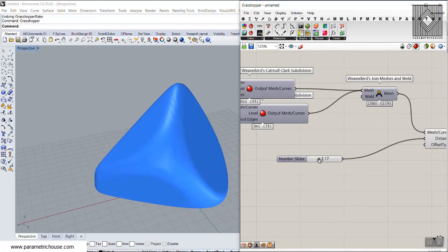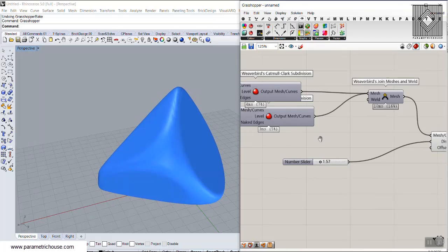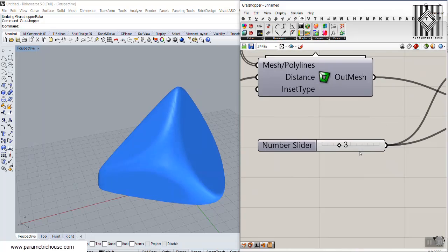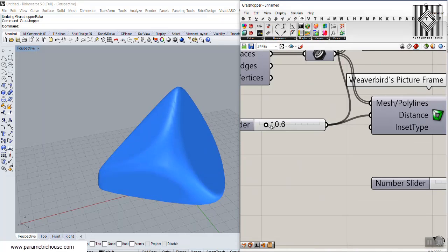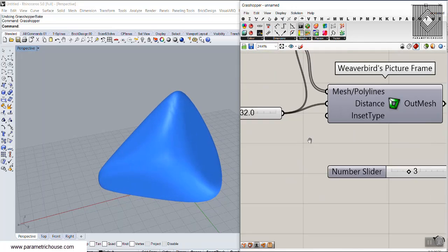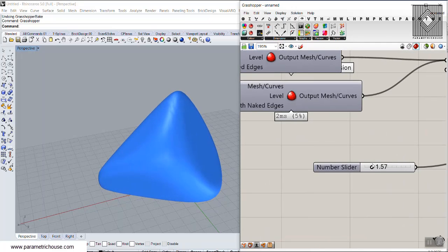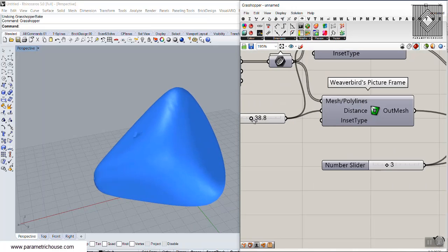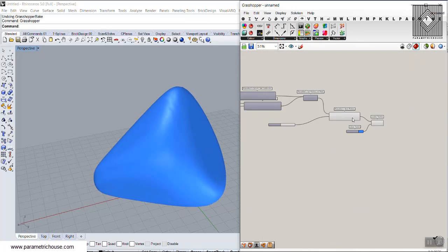This is the thickness, so it's basically a little bit of a scale or something. This is how smooth you can make this. Okay, 3 is enough, and this is the offset. As you can see, when I increase that, okay, we have to increase the thickness for that. Okay, so you can also increase this and have a smooth mesh, as you can see here,